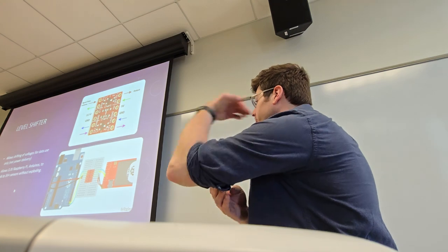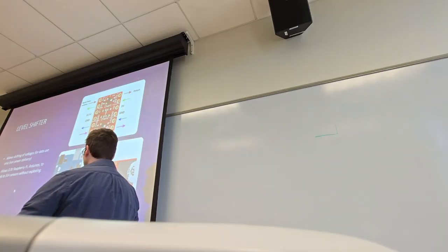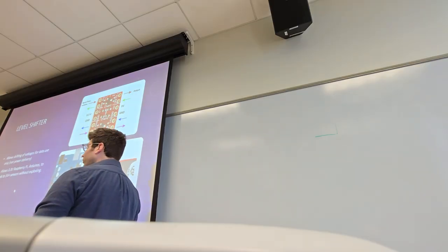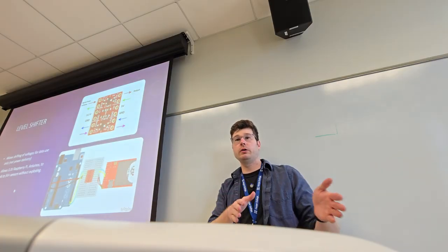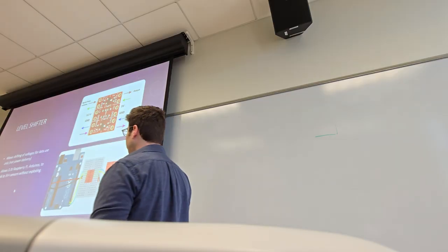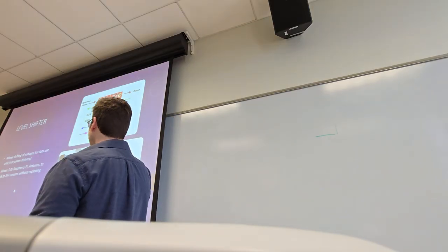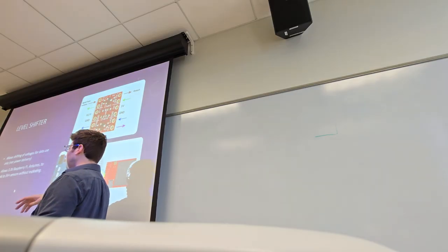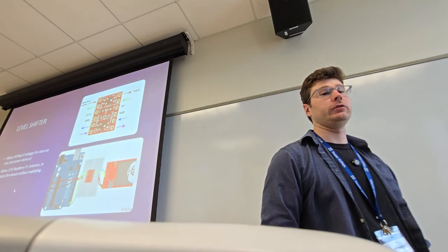This is again where that level shifter conversation comes up. You'll have to look at the sensor that you're using, the motor that you're using. We were talking about motor drivers, right? The things that talk to our motor, in between our PLC or our microcontroller. Those also have certain voltages that they expect to be talked to in. So most will support 3.3 volts, but all might not, right? They might be expecting a slightly higher voltage or a 5 volt signal there. So level shifters can help.